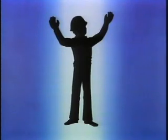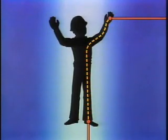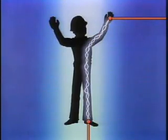The third shock severity factor we're going to look at is the path that the current takes through the body. It's important to note that current will only flow if there is a complete path for it to follow. For example, if a person touches an energized conductor with one hand and another part of the same circuit with another part of his body, the person becomes part of the circuit. In other words, a complete path for current flow is provided, and the person will receive a shock.